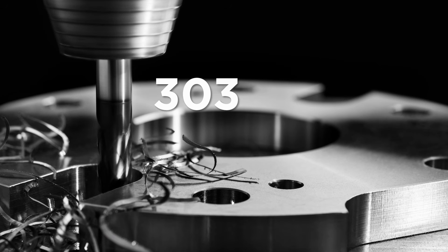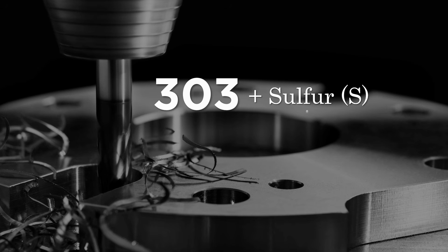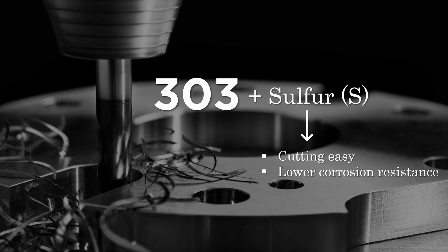Now, there is one more Austenitic stainless steel which is known for its better machinability: 303. This has added sulfur, which makes cutting easy. But these inclusions create weak spots, giving low corrosion resistance, and also make welding very difficult. So 303 is great for machining but bad for welding and prone to corrosion.